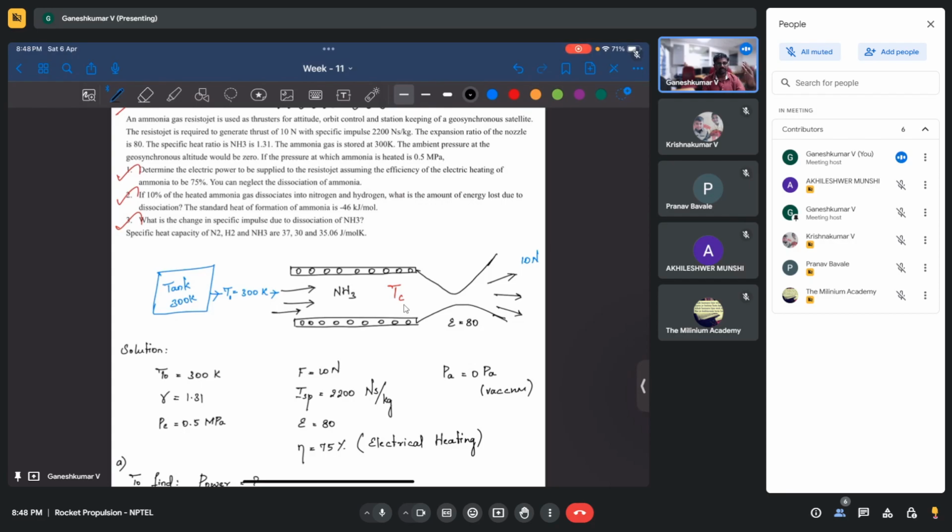If there is an increase in molecular weight, it will be a little difficult to accelerate. So all these three important parameters are going to affect it. Based on this, you can change the equivalence ratio, maybe to the rich side or lean side, and find an optimal point which is going to improve your performance. You are right.